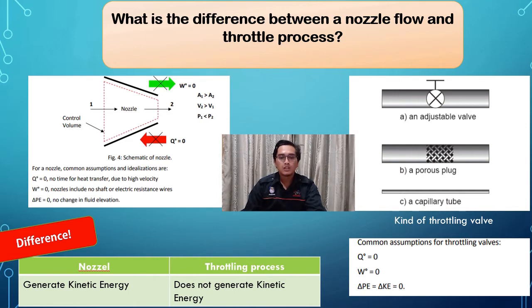There is also no change in enthalpy from state 1 to state 2, which is H1 equal to H2, and this is called isenthalpic. The process will be adiabatic, meaning insulated. The process is irreversible because of some friction of the molecules that makes it irreversible.